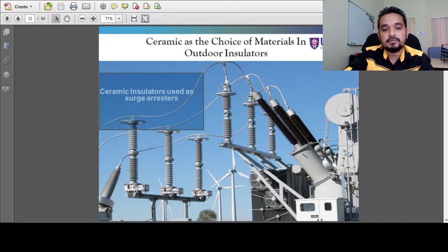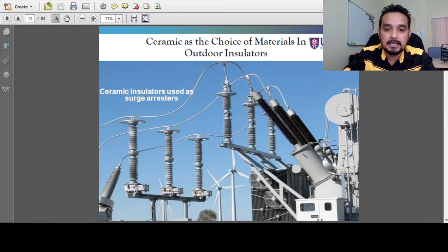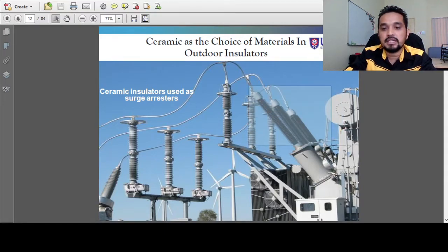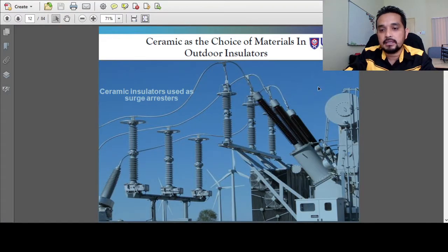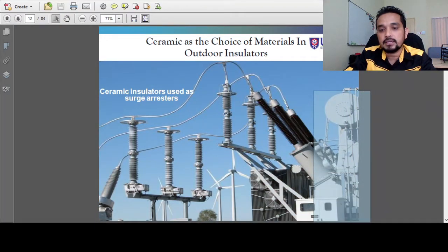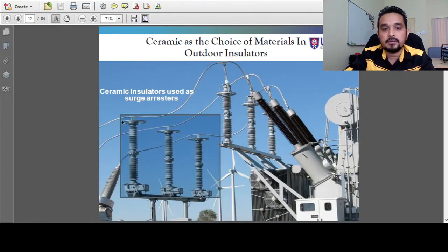Okay, so this is the surge arrestor, for lightning protection, in which in an abnormal case this surge arrestor will operate. And this is the bushing at the transformer, and these are the transformers, right? So we provide the surge arrestor clamped to the power line, before it comes to the transformer, to protect the transformer.